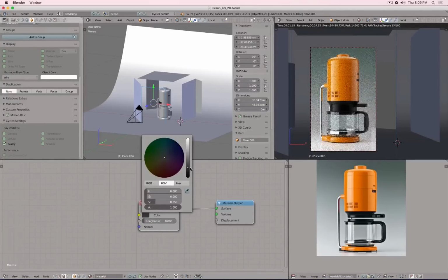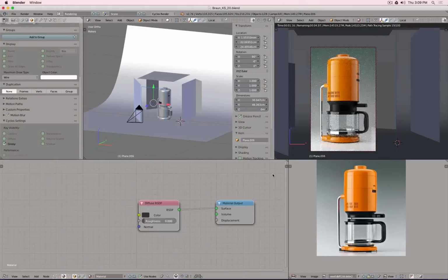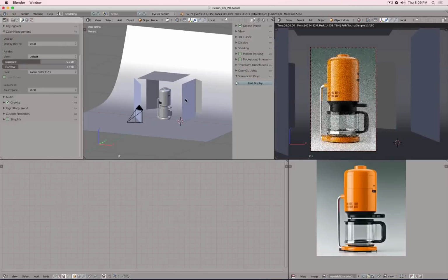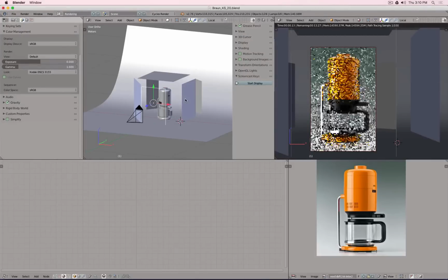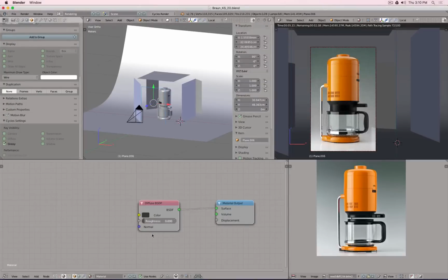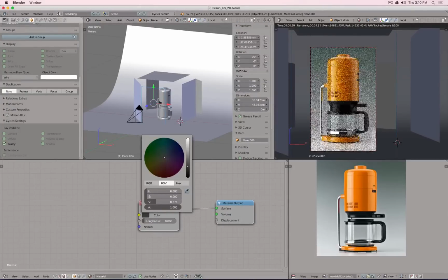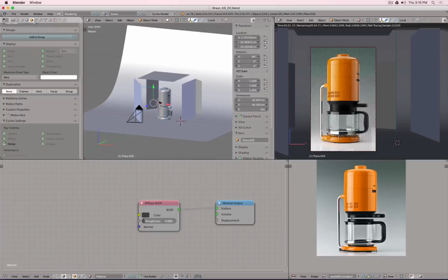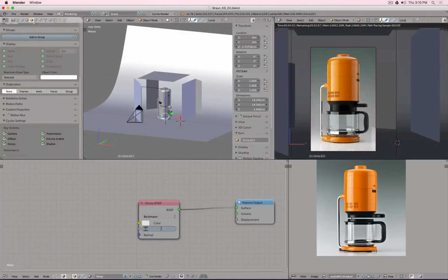See, very often you hear me say something: I can see a bad rendering easily in how empty the reflections are. The reflections here are not empty. They're nicely sculpted and filled. You see this looks empty. This looks more interesting, but this black is a tick too strong, so I still have to make this a little bit brighter there. And also the metal now is super polished, so 0.1. Let's make it a little bit blurry. 0.25. Yeah, like this. Okay.